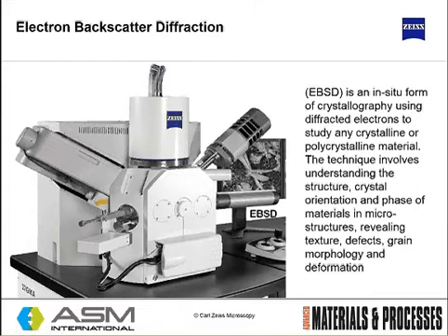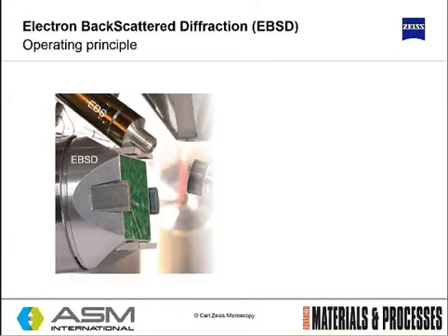So EBSD, let's go into some more detail about EBSD. It's a form of crystallography. The diffracted electrons can study any crystalline or polycrystalline material, and it involves understanding the crystal orientation and phase of the materials in microstructures, but it can also reveal texture, defects and deformation.